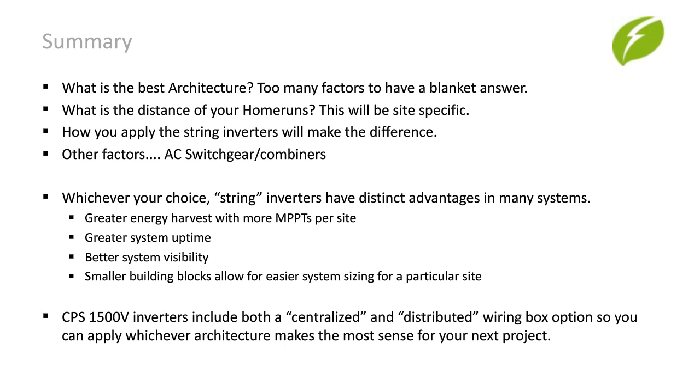What I can tell you from the research that we've done is that the optimal cost of the switchgear appears to be below the 3 megawatt size. There is a limit to the standard ratings of equipment, and combining 3 megawatts of string inverters is pushing it today. As for virtual central pricing, there are so many options available that this will be customer or even site specific as well.